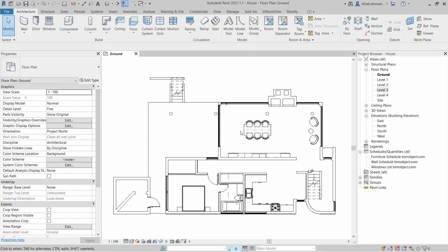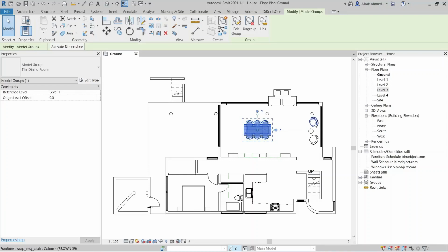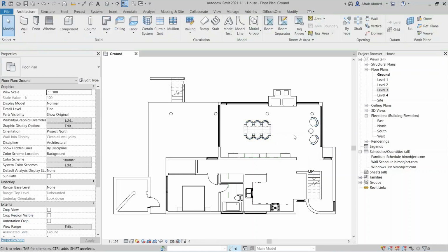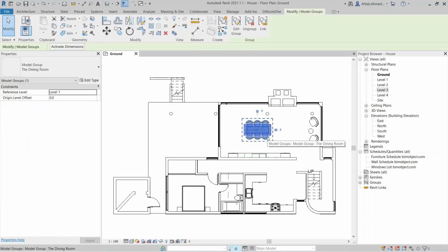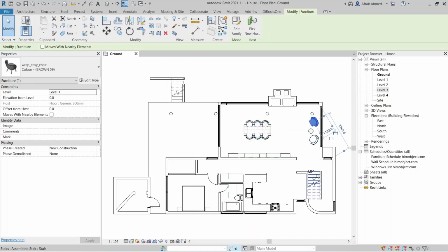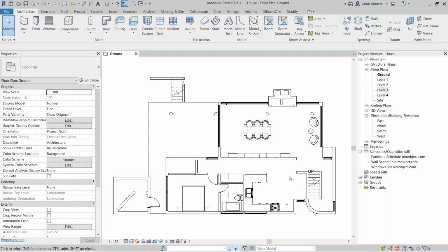A grid is a collection of horizontal and vertical lines creating a pattern against which we can line up our design elements, especially when our design is spread over many sheets. Using a grid makes it easier to understand the design elements in a specific place. Normally, a reference is taken by placing a grid on the center of the column in the project, and the entire project is controlled.